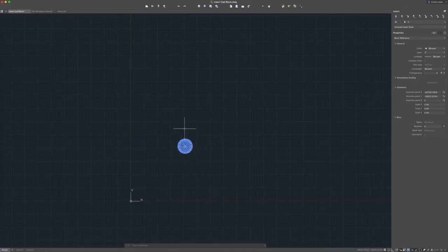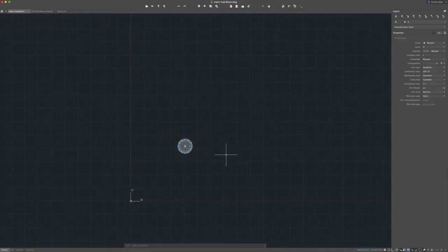And if you highlight this, you can see over here that we have a block reference. Its name is down here, FIA Lin 19. So it's inserted as a proper block. It's on layer 0, and it's just as simple as that. So you can either copy and paste using Control, Shift and C, and then Control V to paste. Or you can go up to your Insert menu and click Block and follow the instructions from there. Simple as that.